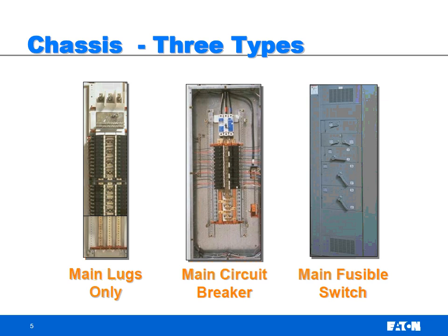And then you have a choice: do I put main breaker or main lugs? Okay, main breaker, there's a couple things it's going to do. Number one, we talked about it's going to protect against overload and short circuits. If I've got a 100 amp breaker here and a 100 amp panel board over here, my choices are: do I put a 100 amp main breaker here, or do I save that money because I've got a 100 amp main breaker here, so I'm protected either way. So that shouldn't be a factor.